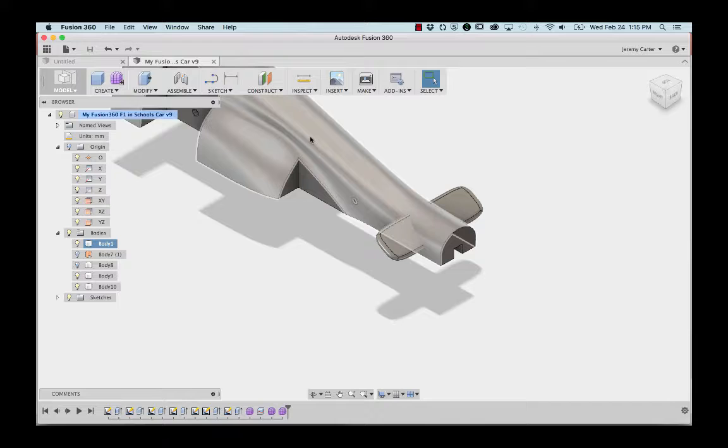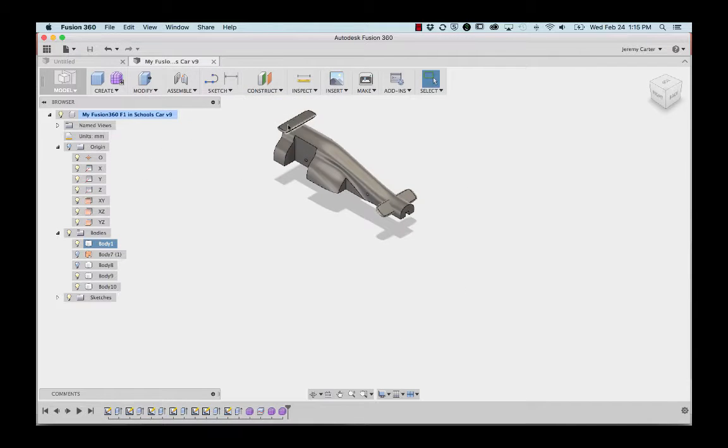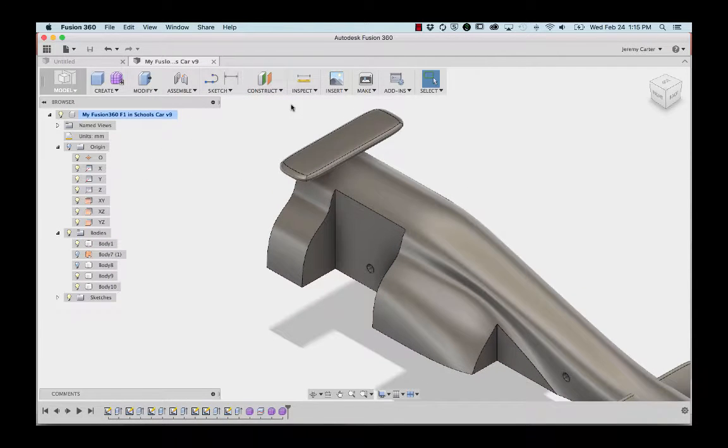Step 2. Add the rear wing supports. In this section, we will be creating rear wing supports, which are the features on the car that connect and join with the wings on the car body. We will start with the rear wings by creating a pad protruding from the top of the CO2 canister housing. On the underside of the wings, we will create a similar but larger size pad.